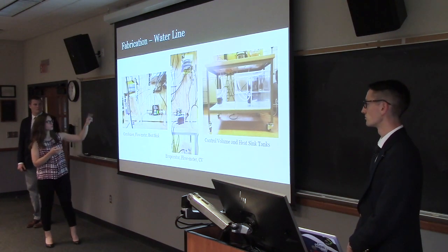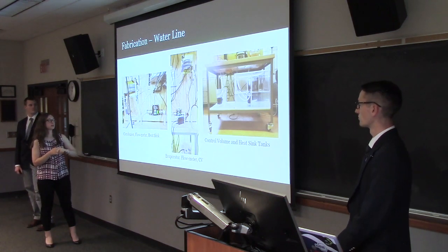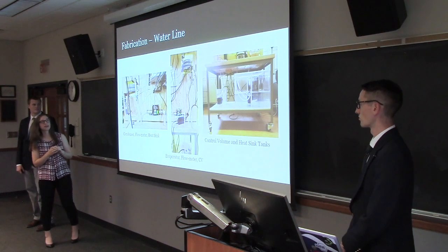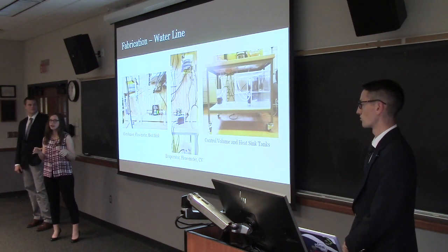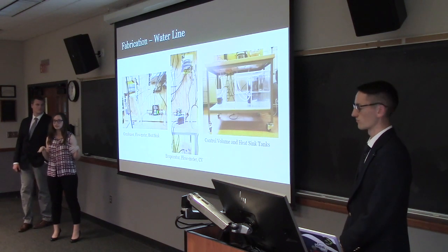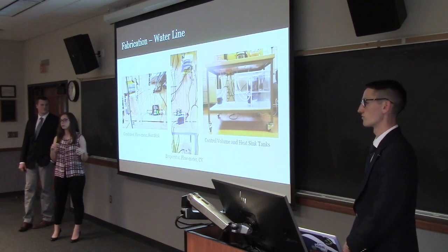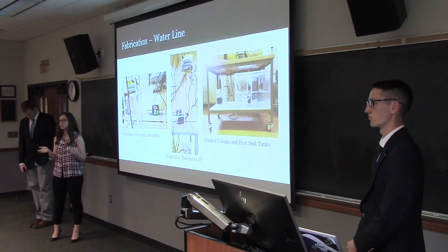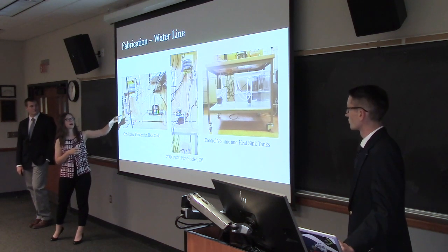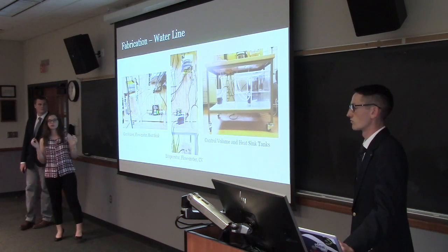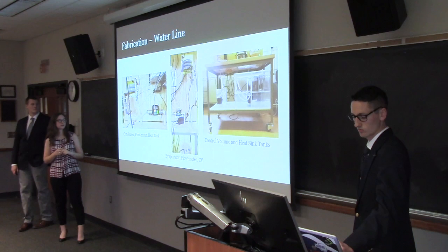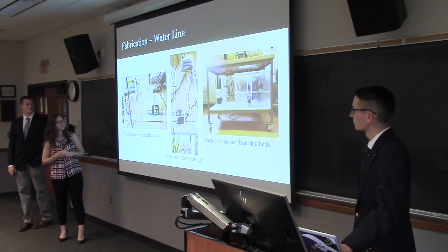And so once we finished the heat exchangers, then was the flow meters. They were mounted to the board as well as the acrylic tanks. Each of them have modified lids so that the tubes could run through the tanks and not have to take the lids off, as well as a thermocouple in each tank to get the final temperature. There's also a thermocouple right at the output of each heat exchanger. All those thermocouples run up to an electronic system there to get that into the deck.